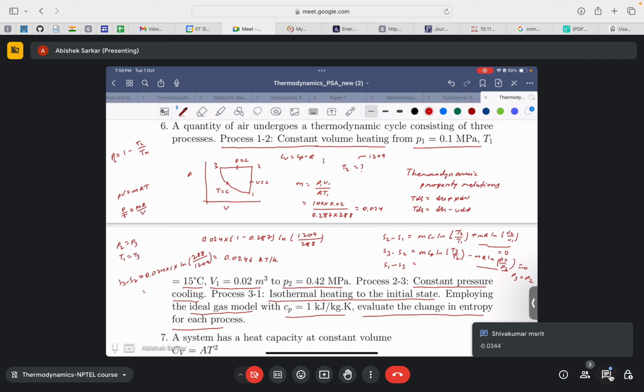Correct, exactly. So you can here clearly see that the entropy of the process has gone down, right? There are obviously some instances where the entropy can be negative, but the net change of the entropy, the summation of the net change in the entropy of the system and the surrounding, has to be positive. Okay, so that's the principle of increase of entropy.